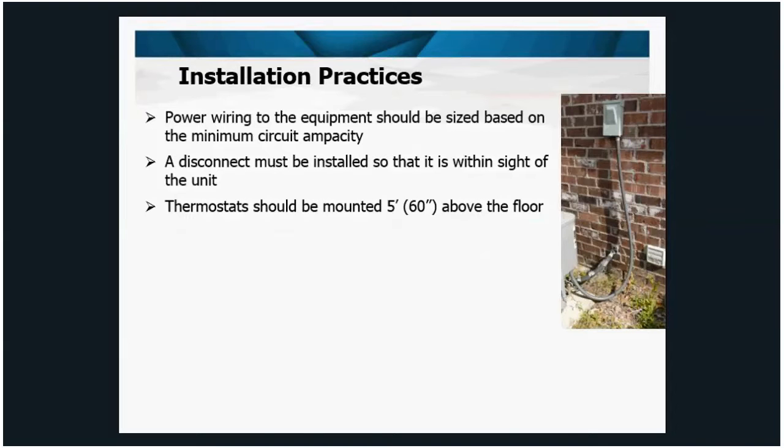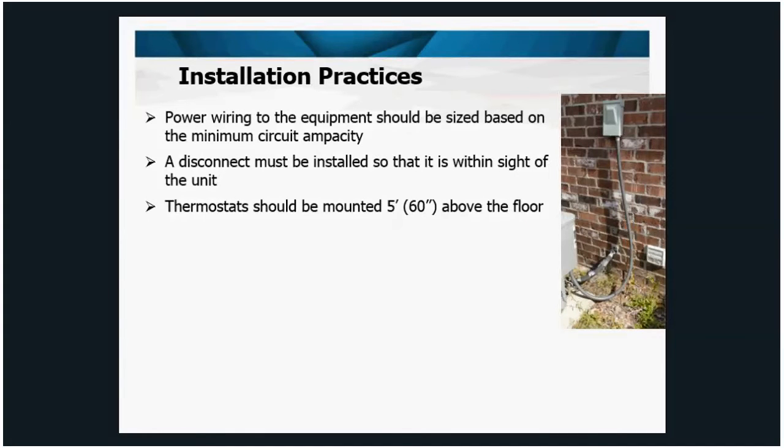Thermostats, and this is a little point of contention, and I think they're going to pull the thermostat questions out of the test. Technically, thermostats should be mounted 5 feet above the floor, 60 inches. But there's the ADA requirements, and that means that